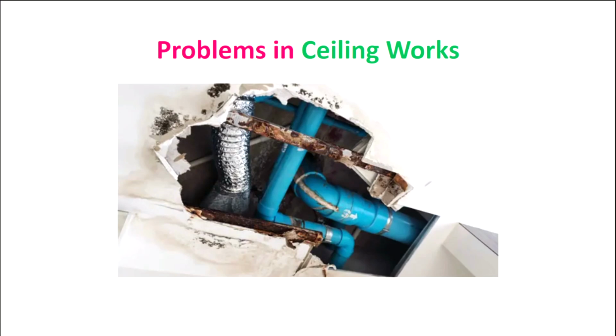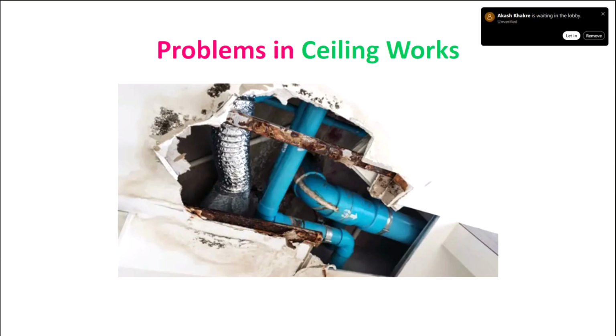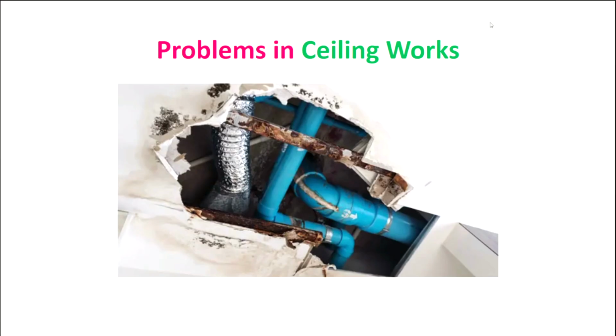Now you can see the condition of the structural members of the ceiling. Now that is getting corroded, and I suppose as civil engineers, although the false ceilings may be looking very good, or may be giving good aesthetic appeal, inspection of all those hangers or whatever the supporting structures of the false ceilings are there, it's very important to see the structural integrity of that also. Because many times we have seen this happen. Suppose they are of some wooden members, then due to termite also it might fall down. But nowadays we are using not wooden members, but there may be old installations where all these things are there.